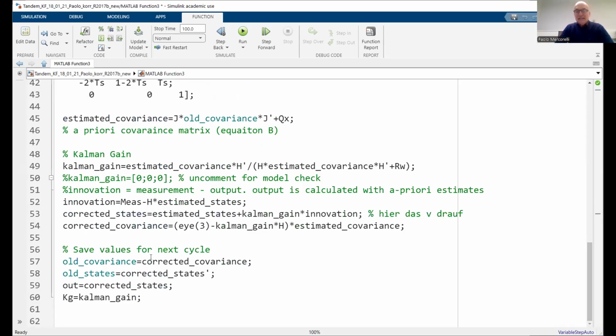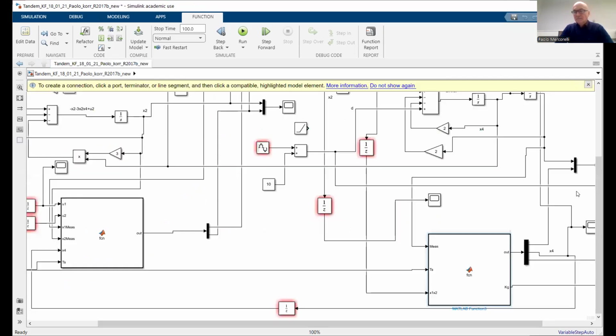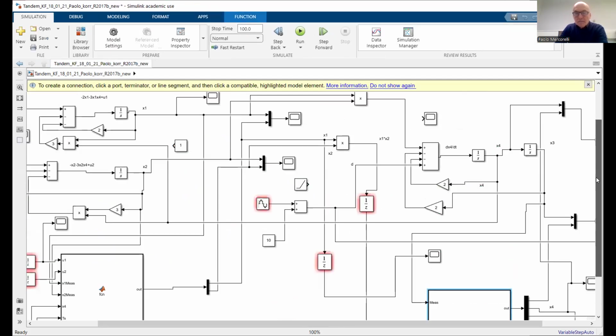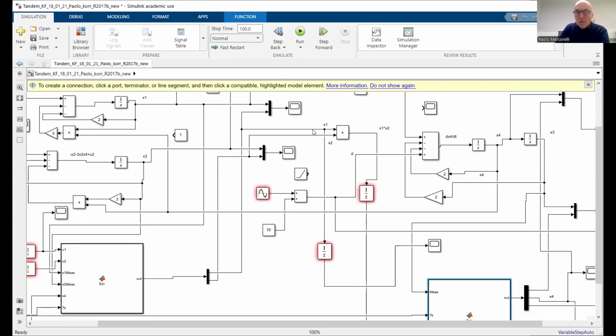Let me clarify this nevertheless. Do you remember I estimated x1 and x2 from the first Kalman filter? Theoretically, this product should be done internally, passing both x1 and x2 and doing the product internally. Please pay attention, x1 and x2 are signals for the second Kalman filter. This means it doesn't matter if I do the product outside or internally. Very important to delay just once.